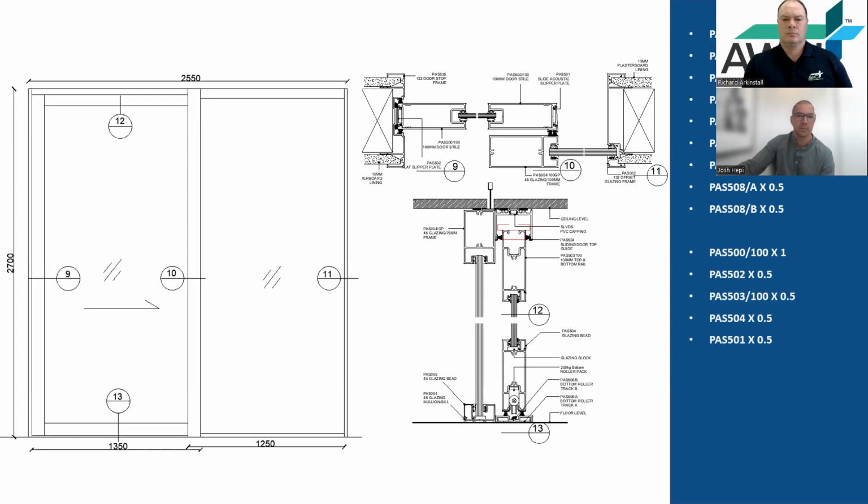Our acoustic slipper on the back is half a length. 4 UC braces again. A smaller mohair, which is the mohair that typically works in all our door suites or inside our door profiles, which is our mohair 4.8mm. So I just basically go 1 length there, 1 length there, 1 length there, 1 length there, 1 length there, 1 length there. So 6 lengths times 2.7, which is the height, and then work out what's required inside the top track as well, which is the same, 4.8mm, and it comes out to roughly 22 meters.